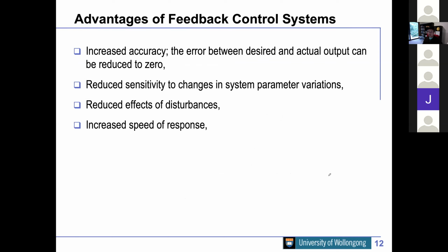The main reason we require feedback control is because of two things. One is if the model of the system is not accurate. If we have a perfect model, then we don't need feedback control. Like if we know exactly how thick the bread is and how many minutes the toaster requires, we have a table listing it in the kitchen, and you have a ruler to measure the bread thickness, then you don't need feedback, because you know the time compared to how well it's cooked, so you just set a time. There you go, that's okay.